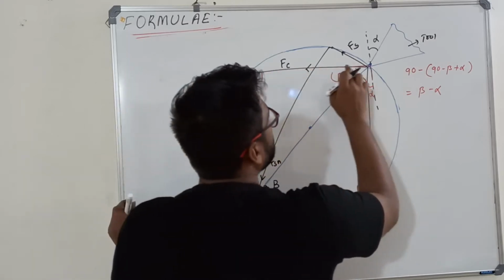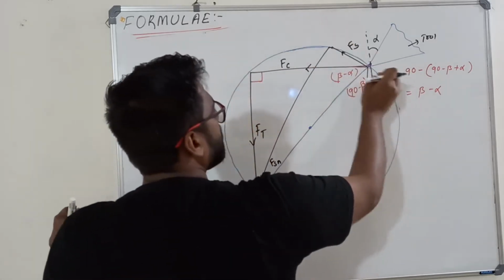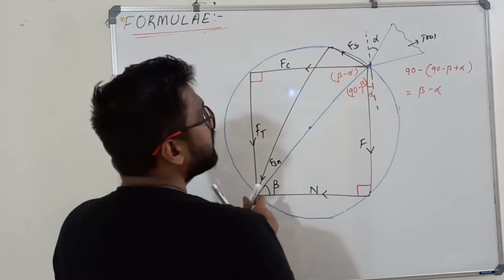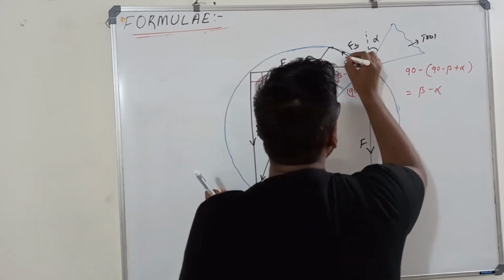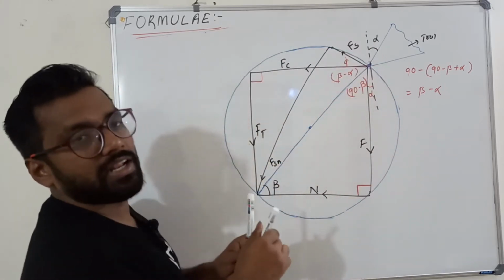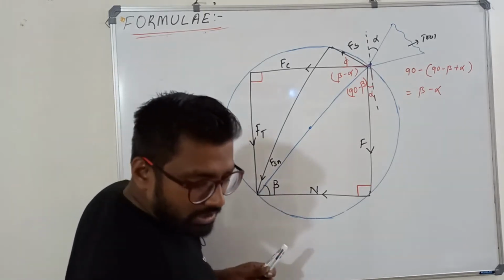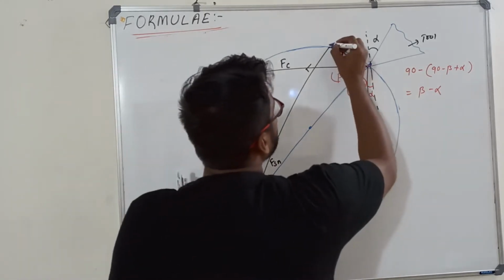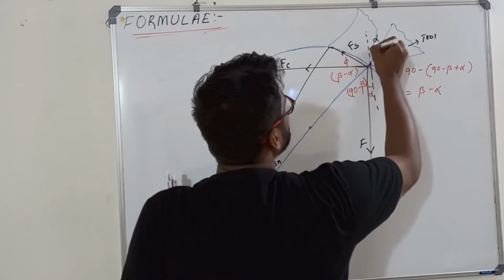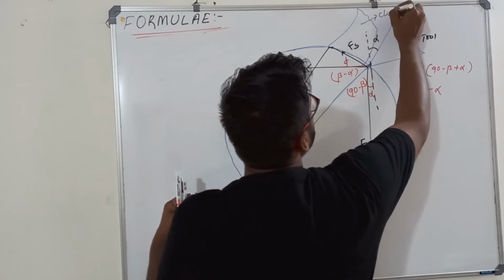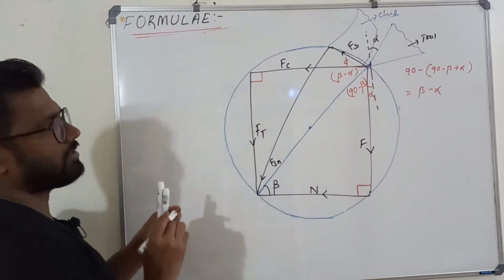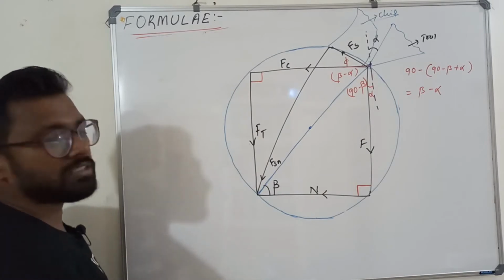What is the angle between the shear plane and the cutting velocity? What angle do we call it? Sir, we call it shear angle phi. If you remember your drawings properly, this shear plane angle, this is your chip. So this is your Merchant circle.